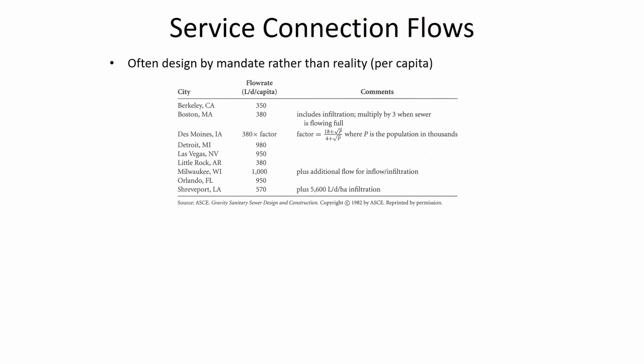It can be related to climate factors, where maybe they're expecting there to be a combined sewer in Milwaukee, which is that there would be a lot of stormwater influence in a sanitary sewer. But it could be, yeah, Berkeley, fewer showers. That's as likely as anything. But the point is, when you're doing sewer design, you need to be acquainted with the local ordinances, and sometimes they diverge from reason and diverge from engineering logic.